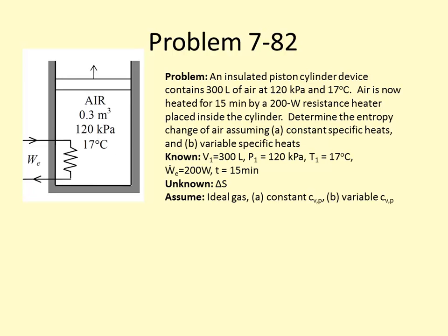One of the reasons that it's the same is because the pressure in this problem is the same. It doesn't vary. So when you have wide pressure variations, then this approximate approach differs more widely from the exact approach, given the same temperature interval. And then, of course, as your temperature interval increases, it becomes less and less accurate because the specific heat is not necessarily linear over a large temperature interval. And when we calculate the average specific heat, we're assuming that it's a linear relationship.